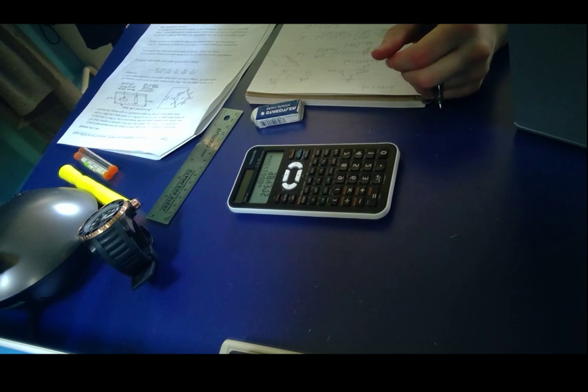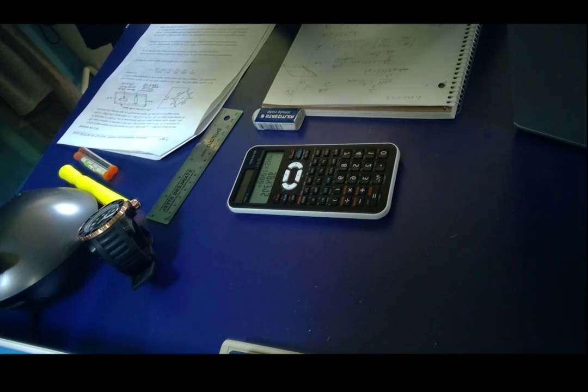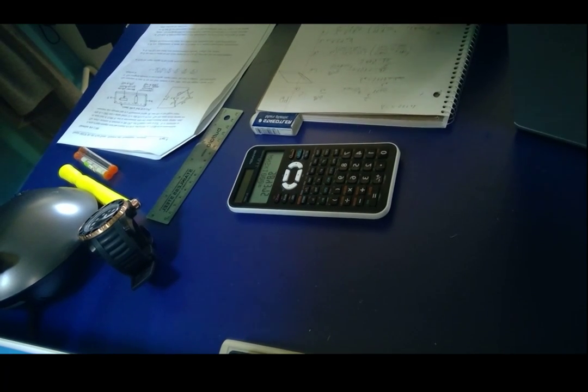If your measurements of strain are to be made in a variable temperature environment, describe the modifications you would make to your instrumentation with justification. All right, so variable temperature environments. So we know that R1 and R3 work together, and R2 and R4 work against. So what we would do is, if we assume that the transversely mounted strain gauge will not expand, and if it does expand, then we have to use a completely different piece of metal. Or we can just put it on the side.